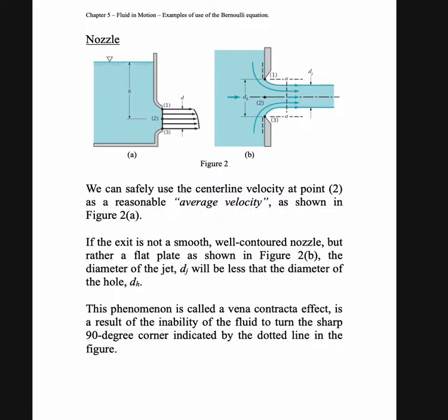about the pressure, the pressure for the moving fluid at this point after it passes through the nozzle is equal to P atm. So you could assume that it is equal to 0. However, the fluid flow or the diameter here will affect your calculation of flow rate.